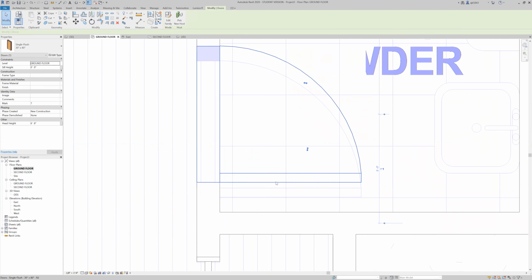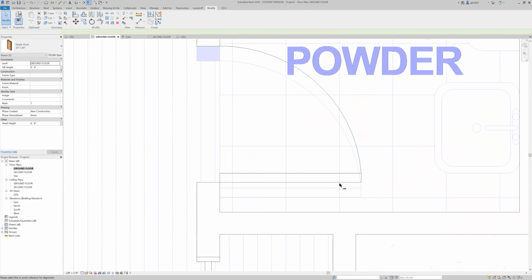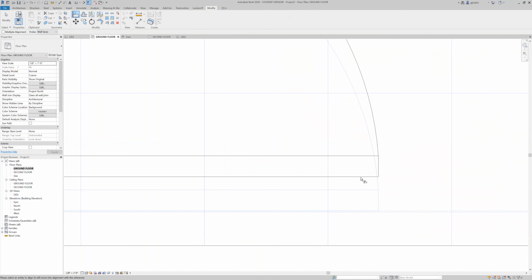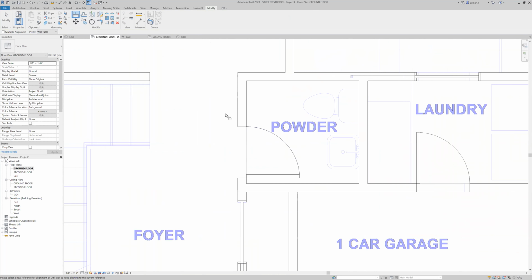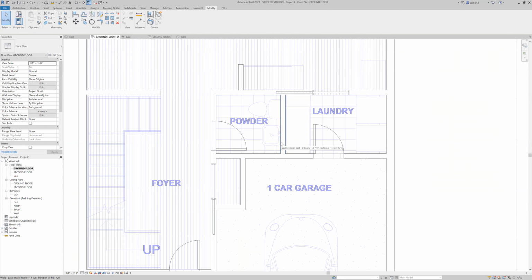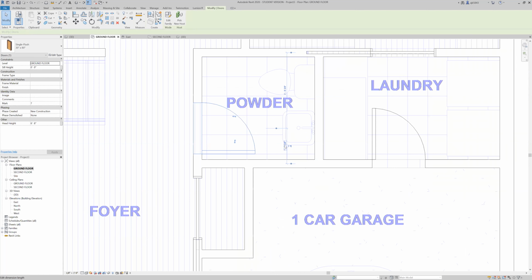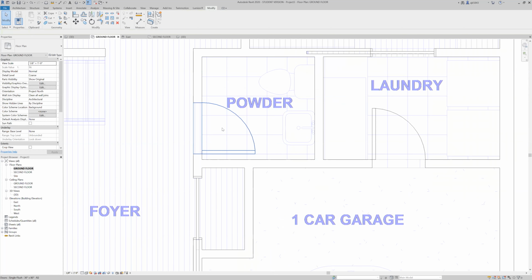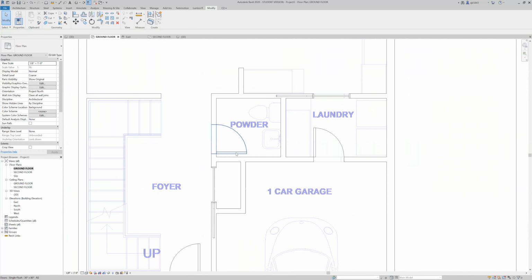So typically your best bet for this is to use that align tool and go in and grab each one to make sure that they're going to hit as to the specifications of your CAD plan. Oftentimes you might work in CAD and just maybe only design the walls. So placing doors in Revit, you may decide that you want a consistent offset from your walls or some other different parameter to keep all of your doors consistent.